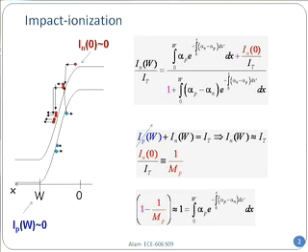And I_N at W over I_T, is that equal to 1? Almost equal to 1. Do you see that? Why? Because most of the current which is getting out at W is the electron current. I do not have any hole current. So therefore, I_N at W divided by I_T is very close to 1. So I cross multiply the whole thing and just exchange sides. And that will give me this very simple relationship.